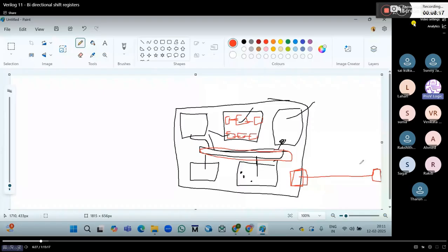If you observe here, we can see two types of communication: parallel communication and serial communication. The processor wants to communicate with the keypad or some USB protocol. The processor always takes parallel data, and it works at high speed and high bandwidth. Whereas a simple keyboard, mouse, GSM module or Wi-Fi module works at a low bandwidth.